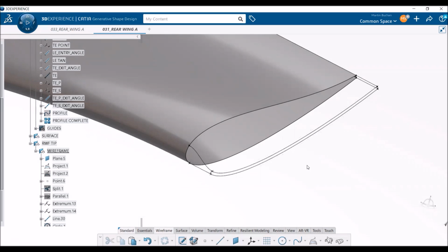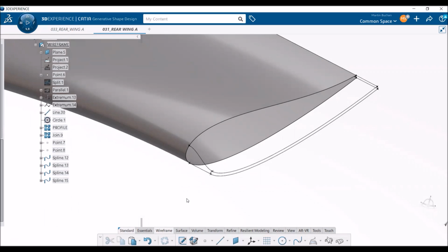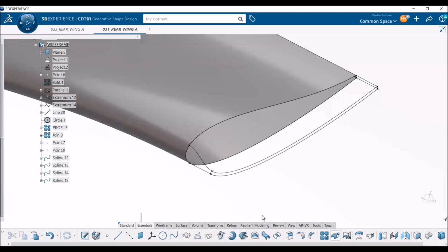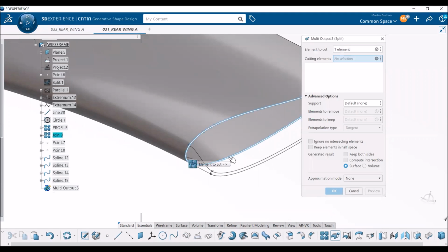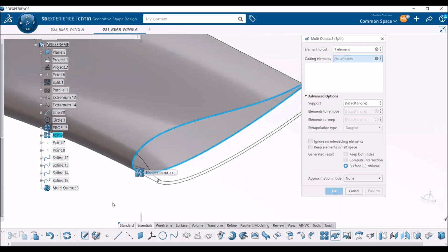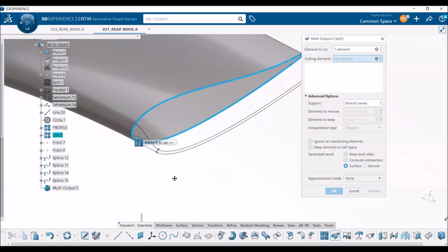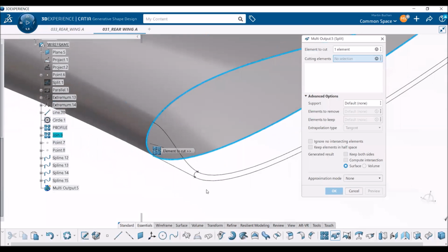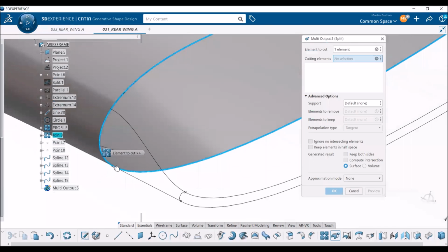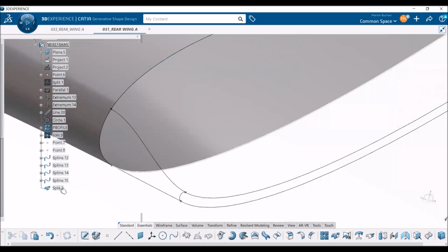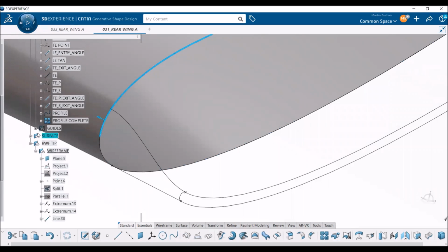And for our outboard new feature, we already separated all the different lines from each other. We now need to do the same thing for the wing profile. So we have the profile here, and now we use the 2 points at the leading edge to separate that. So we use this point to separate the lower part, that is only the lower part. Then we do the same with the upper one and with the leading edge itself.